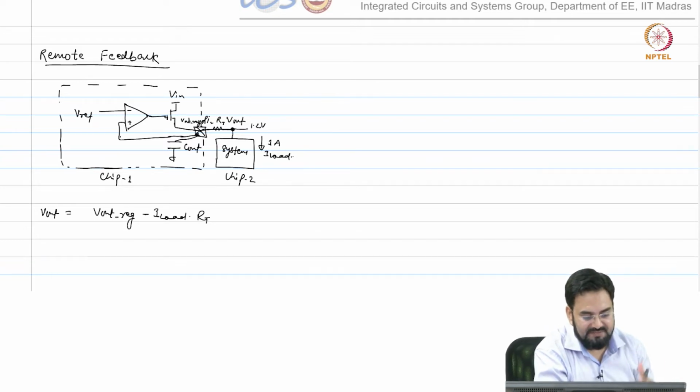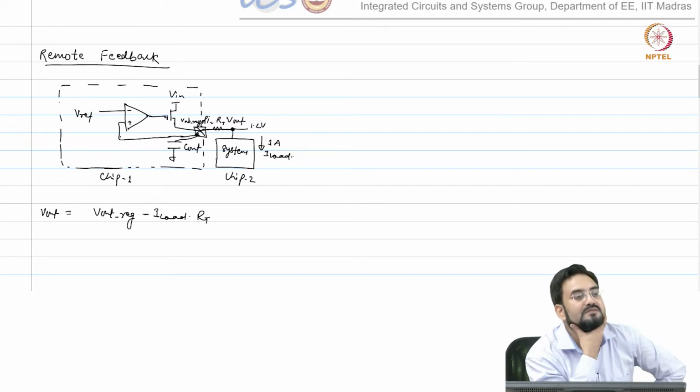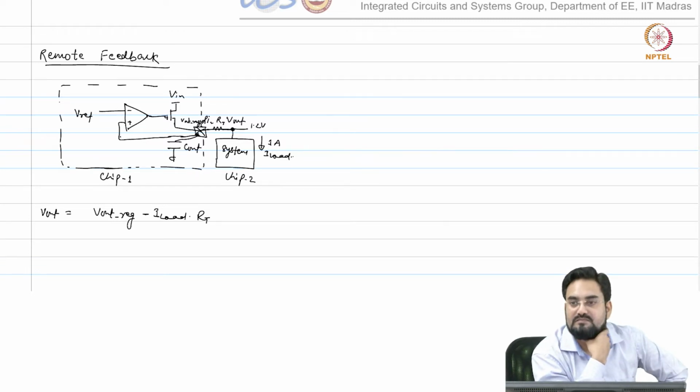So, how can we fix this? What can be increased? Wire width can be increased. No, but that will cause something. You will need more space on the board, and you have limited space. You cannot just make your wire as fat as possible.